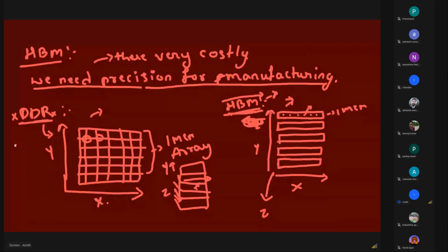If I can tell you one example, you can't use it in the DDRs. We have one feature which is training, retraining and write training. Before doing a read or write normally, whenever your PC boots up, we need to train this DRAM to do the work normally. But in HBMs, we don't have that. Why? If you're consuming more time in this training, how can you make efficient use of this HBM, correct? So that is the reason. Whenever you are using the HBMs, you don't have to train them. They are already trained. You can directly plug and play.